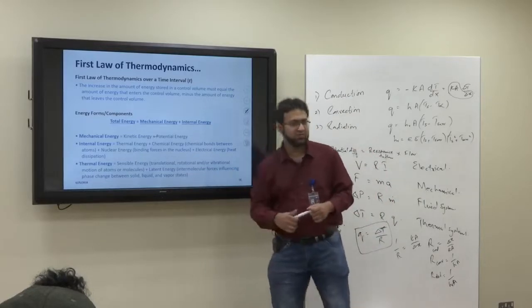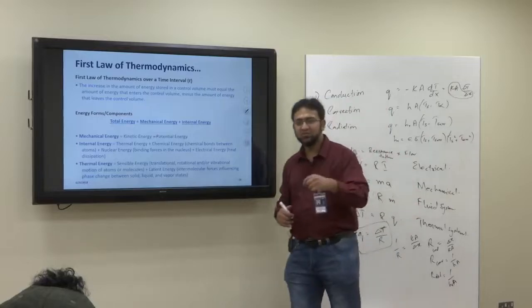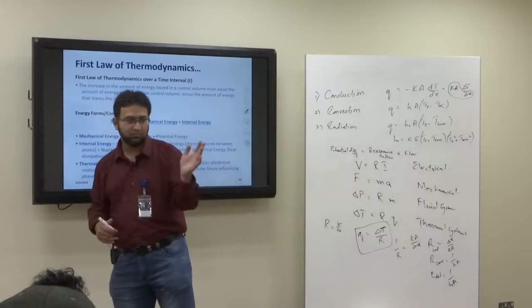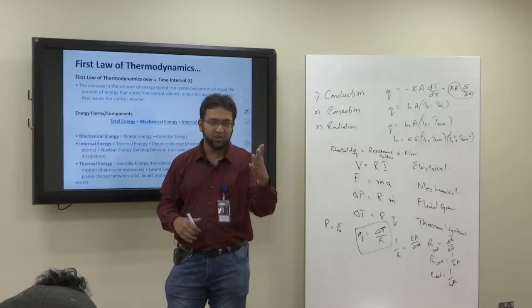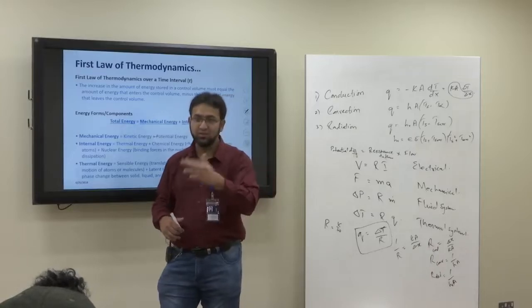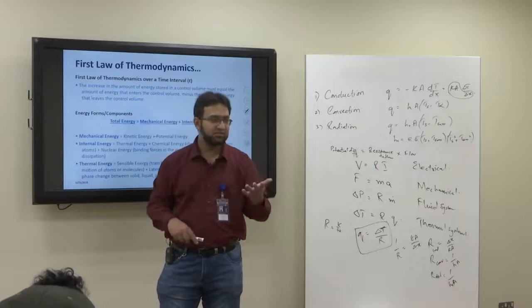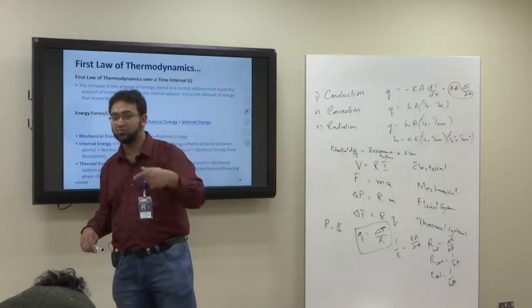Do you know the concept of sensible and latent energy? Any energy which can be sensed by a thermometer is sensible energy. You have water and you start heating it. The heat is being supplied to the water and you can sense it by the thermometer as the temperature rises. That's the sensible energy. But once water reaches 100 degrees centigrade, it is about to boil.